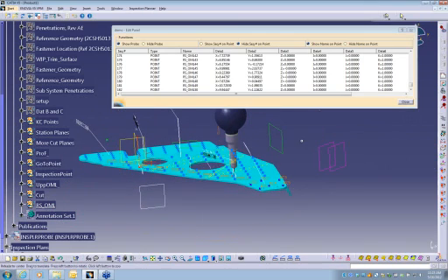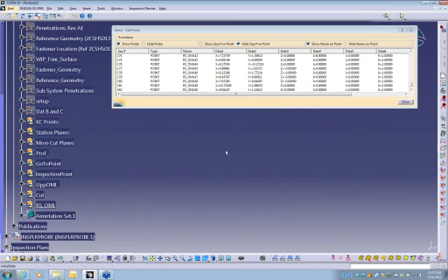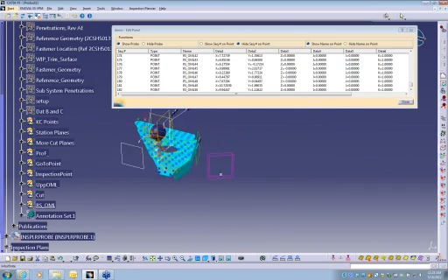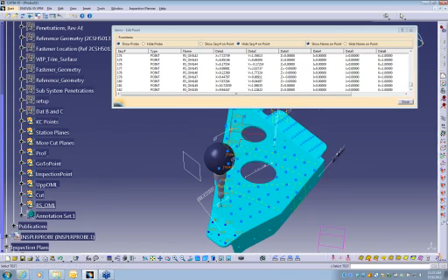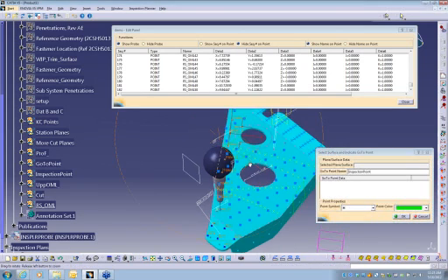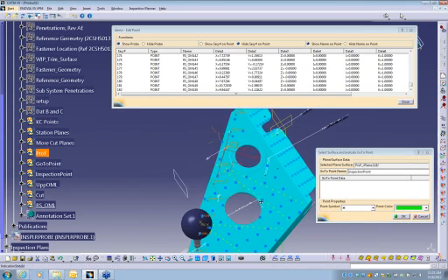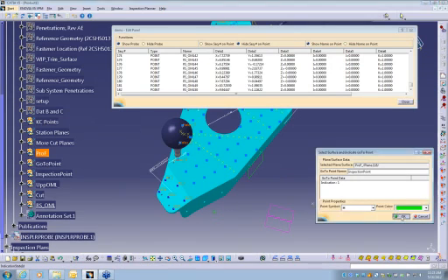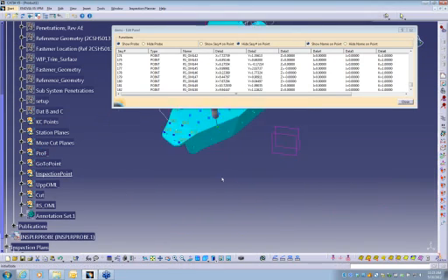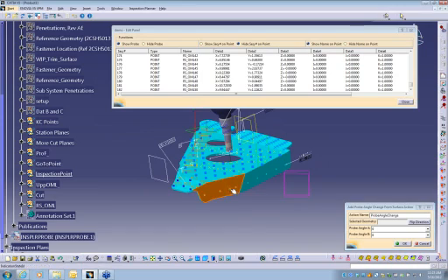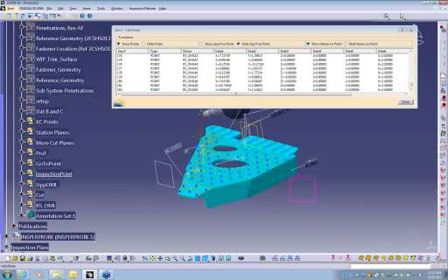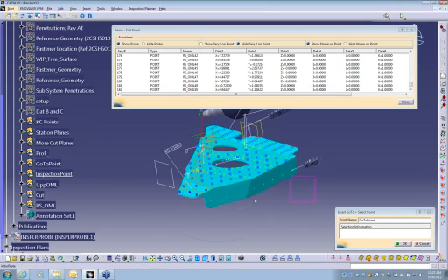Another great way to make points is, let's say engineering requires certain station planes to have points taken on. So let's come over here and we'll do another probe change. We'll use this plane that we have here. We'll send the probe over to here above the part. Okay, and let's take advantage of the smarts of CATIA. We'll come in here. We'll set the probe angle. And then we'll go back to the point that we use for the go-to move.